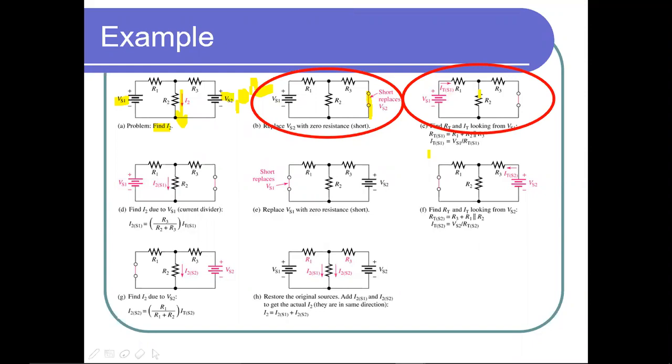Here, R2 and R3 are both in parallel, since the short circuit connects them. This R2 and R3 parallel combination is in series with R1. Then you will get the total equivalent resistance RT. I am mentioning the total resistance RT when using supply 1, so I include the suffix: RTS1. To find the total current using RTS1, you should use this resistance.